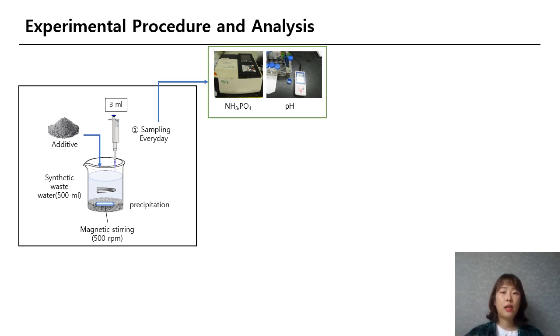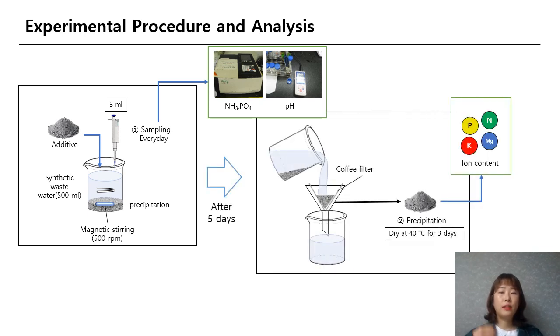After 5 days, wastewater was filtered using a coffee filter and sediment was dried at 40 degrees Celsius for 3 days, after which they were analyzed for heavy metals.